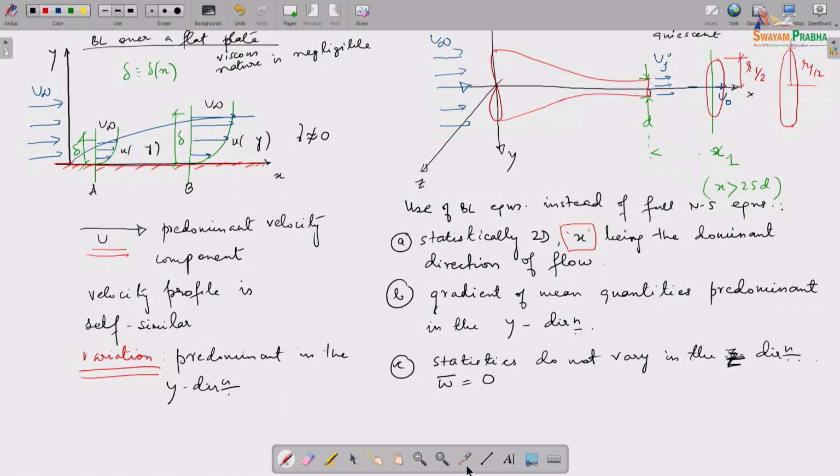Similarly, within the turbulent jet, of course there is turbulence, but outside of r half, so to speak, it is quiescent and turbulent behavior is not there. You can represent your flow there, it's quiescent, with density just rho, whereas here rho is equal to rho bar plus rho dash, a mean quantity and a fluctuating component.